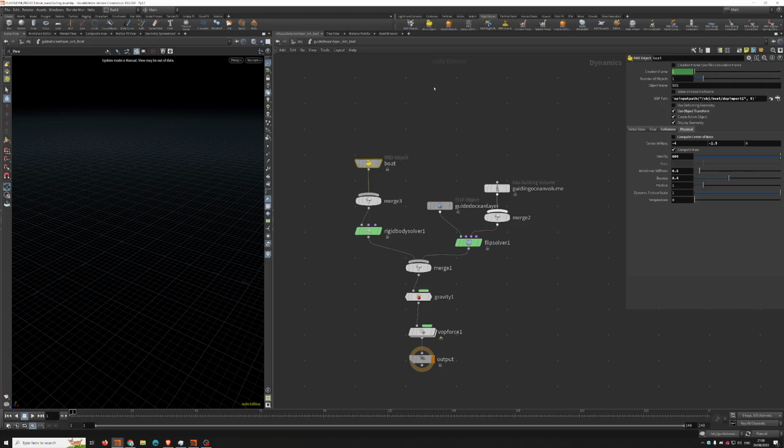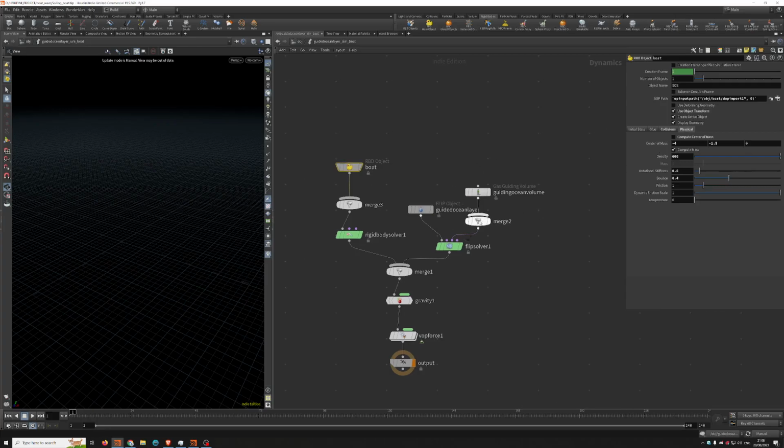It's very difficult to get it to work in the first place, because you need some iteration to get the right center of mass, because when you change it by hand, you have to find it, and also the rotational stiffness and the density. You have to play with these three parameters and iterate until you find the right values.